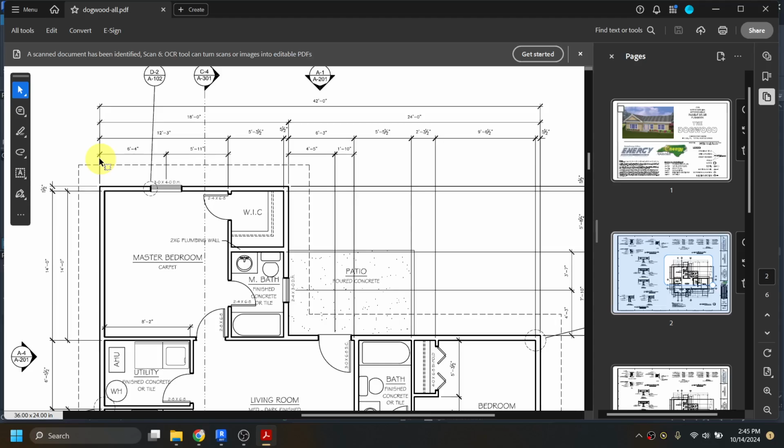So we want to keep pretty construction-friendly numbers. Now, one thing I will say is that this window here, from our face of stud to the center of this window, is 6'4". If your window's at 6'5", I'm not really going to care all that much. I'm just going to be looking for construction-friendly numbers. If it's 6'4" and 7/32, that's really obnoxious, and you can move and adjust pieces around. We also always want to make sure that we're taking our measurements from the face of our studs.